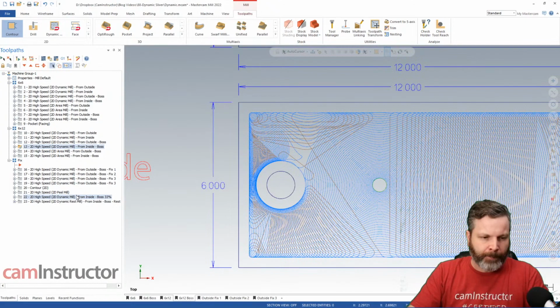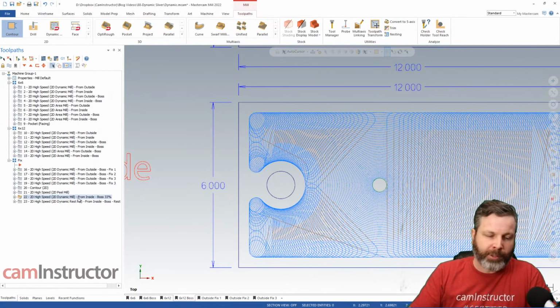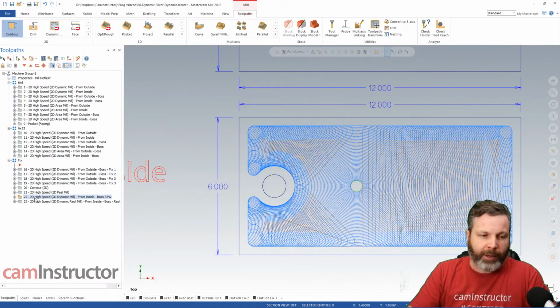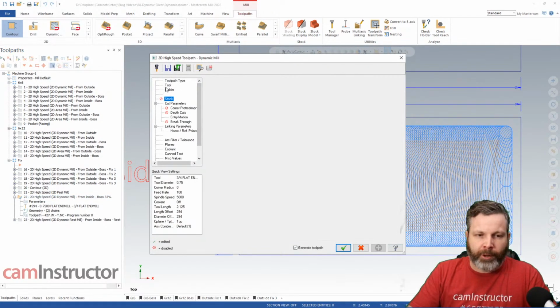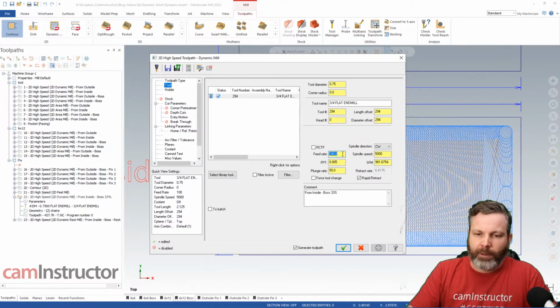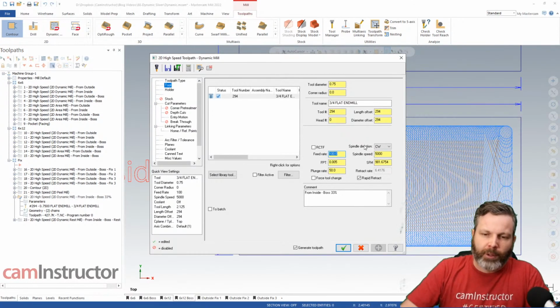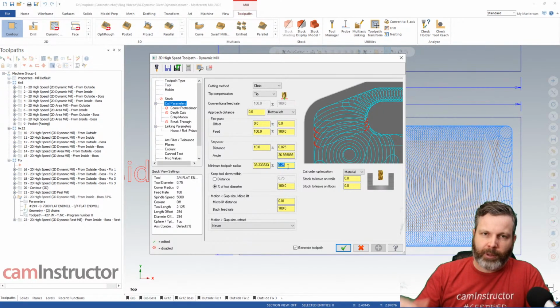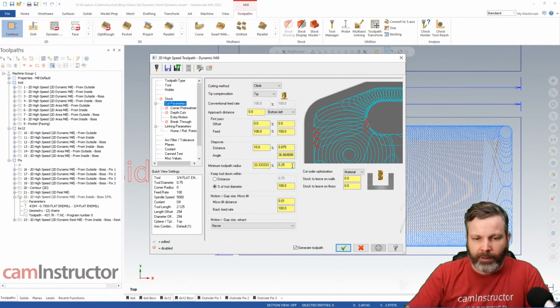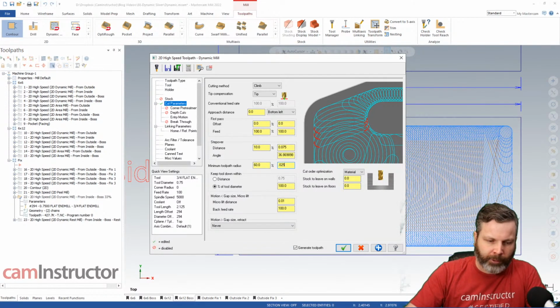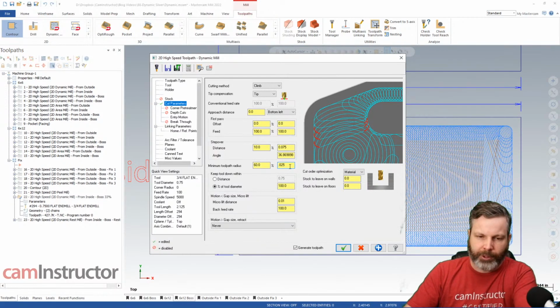So what we're going to do here is just not cut it. Plain and simple, we're just not going to cut those areas of the tool path with our tool at the higher feed rate. So this, to be even more exact, maybe this is 300, 250, whatever it is. And with this, we're going to limit how small we can get with this tool path. So I don't want this to cut anything less than a 1/4 inch radius. You want it to be extra safe, call it 400, call it maybe 60%, whatever it is. But I'm going to leave this at 1/4 inch, not 25 thou, sorry, 1/4 inch. 1/4 inch for now.